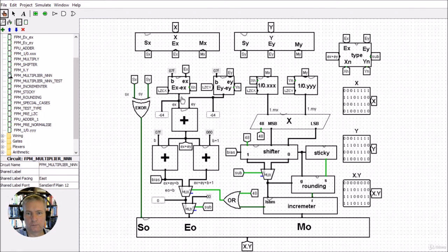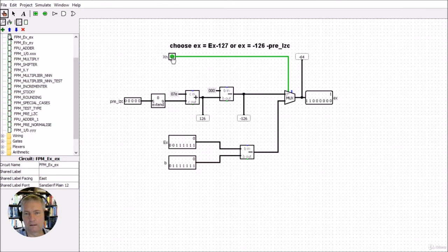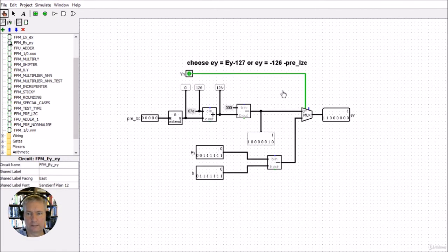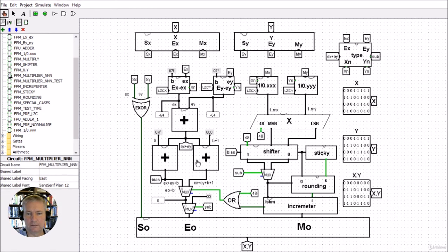Now again, we work down through and we have our value here for our x, which is a normal value, which comes through here, and we've got a value for our y, which is a normal value again, and it comes through this route here. Then we do the additions here, but when we get to the bottom, you'll notice that in this instance we've got a 48th bit as a high bit, and you can check that on the multiplication tool in the Excel VBA. So it's going to choose this path here, but it doesn't really matter when it gets down to the bottom because it's a subnormal output. A subnormal output just forces the outputs all to 0. So we get all zeros for the output.